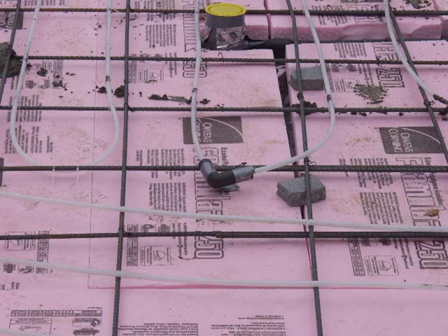Now, in general, we try to avoid putting any joints of the tubing in the slab. The technology has advanced such now that it doesn't really matter, and the joints are very, very reliable. Nonetheless, if we do have a joint in the slab, we'll wrap it with pipe insulation and tape it all the way around so that there's no likelihood for that joint to expand and contract should the floors get cold and then warm back up and cold and warm back up. Because the actual fittings themselves are made out of metal, we want to keep them as insulated as possible from any fluctuations in temperature in the slab.